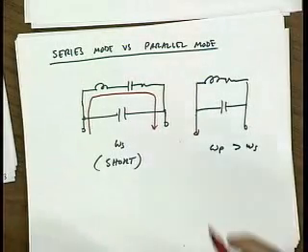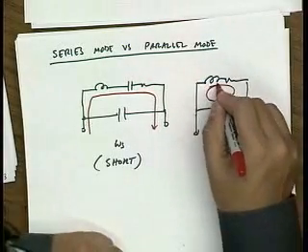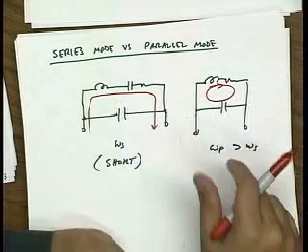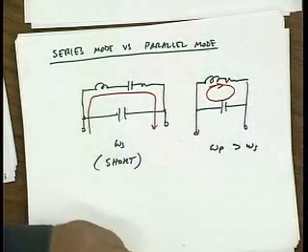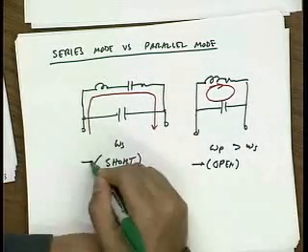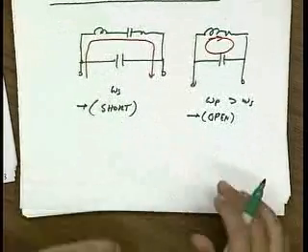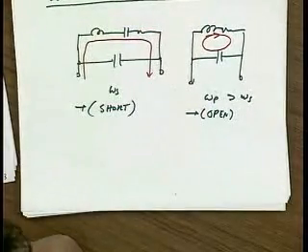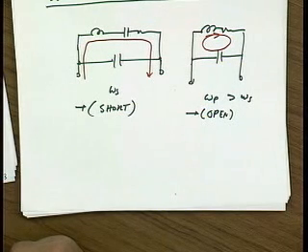So in parallel resonance mode, there'll be a resonant current circulating here, and from my terminals I see very high impedance, or practically an open. Sort of. Okay. And in general, we can see that the parallel resonance mode is higher than the series resonant mode. Okay. That makes sense to everybody?